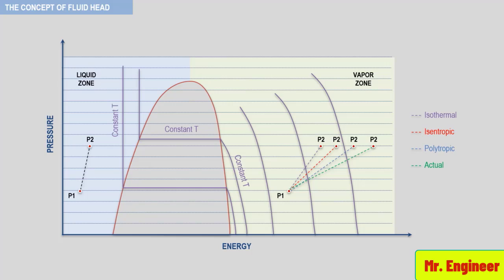This is because for a given compound, its mass is lower in the gas state than in the liquid state, and therefore a much greater amount of energy is required to compress the gas the same amount than the liquid. You can refer back to a previous video of this section and study the equations that were used to determine the head required for a liquid and a gas. In addition to many more parameters being needed for calculation of head required for a vapor or a gas, certain ideal assumptions must be made. We'll introduce them in the next couple of videos.